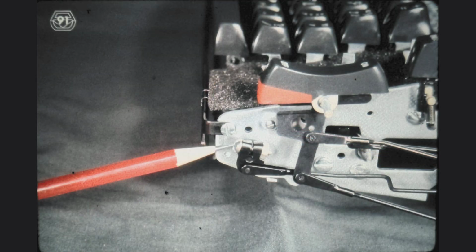When we adjusted the keylever upstop, we also changed the position of the shift keylever, and we must therefore readjust its connecting linkage to the shift clutch. In order to obtain maximum transferability, we must have an ideal length for the shift keylever pawl. When we have a transfer of motion from the shift key to the shift clutch latch, or release arm, we have to position this clamp so that when the keylever has traveled halfway down, the point of connection between the clevis and the clamp is located exactly underneath the pivot point of the clamp, or simply, directly under the shift pawl. This ensures equal over-the-center travel for the clevis.